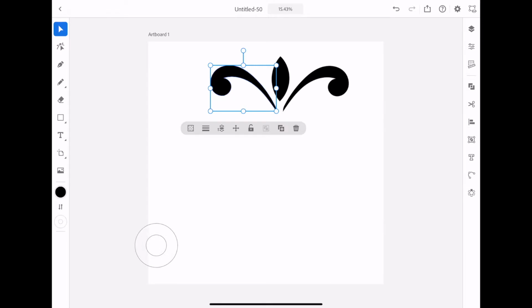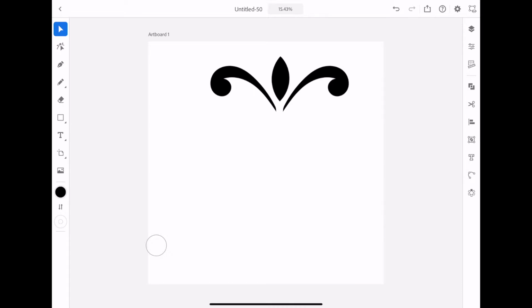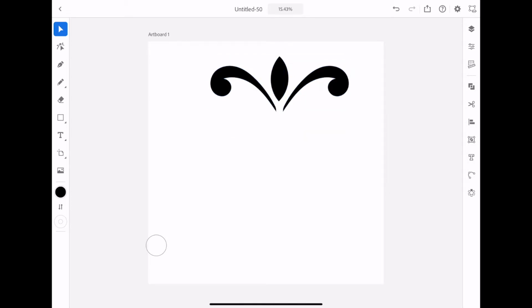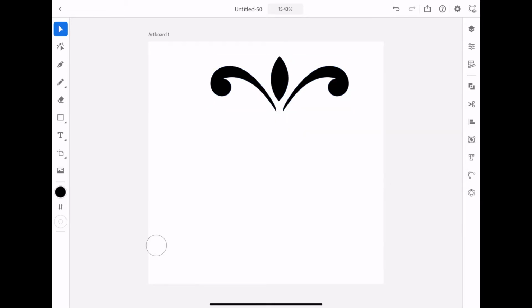And then I select both elements and I align the two elements so they're horizontally aligned. Select the three that are on my screen now, and I'll distribute the distance between them, so now I've got the right distance between the three elements. That looks good. Okay, select it all and then make it one group. Now it's one group. Okay, so I'll move on to draw another element.